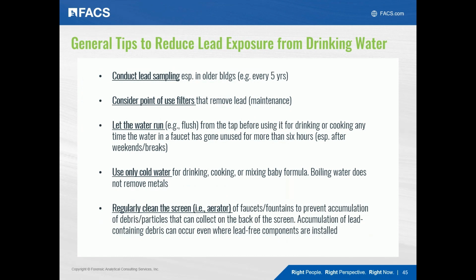And then finally, if there's screens or aerators in your faucets or drinking fountains, make sure that they are regularly being cleaned. Because you want to prevent accumulation of debris and particulates that can collect on the back of the screen that can contain lead.